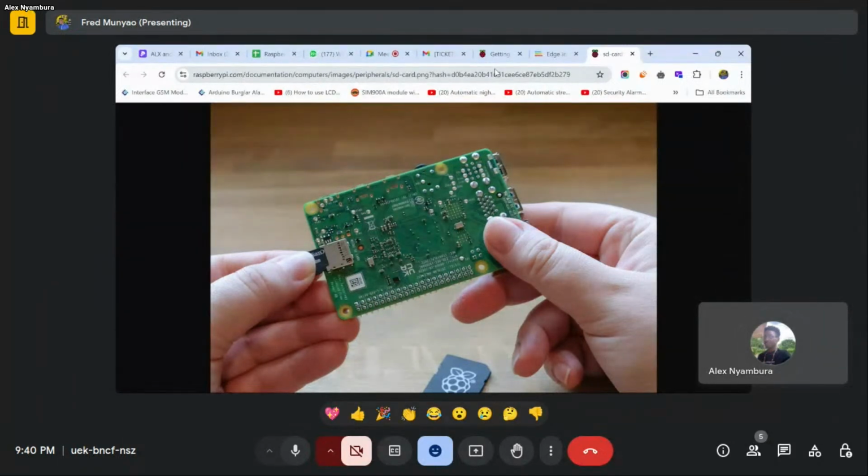One is UART, and we also have SPI. You can set one Pico as master and the other as slave. The master will be commanding the slave, and they will be communicating throughout. Any other question?